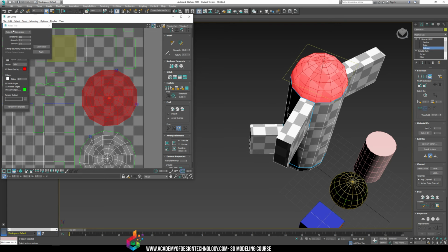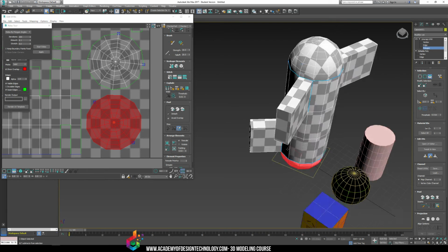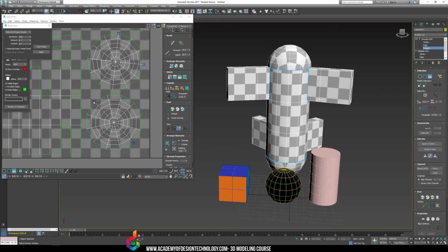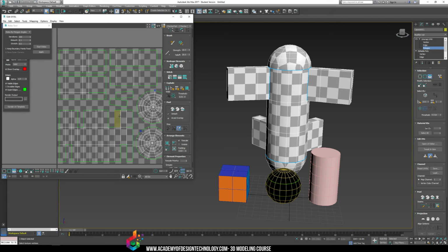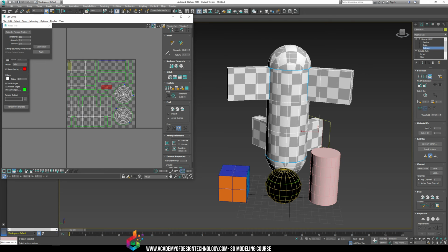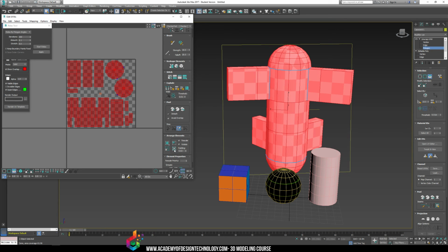But we can fix that with hopefully some polygon angle changes. Yep, relax by polygon angles. Worked a lot better. And there you go. Much, much better way of handling it. And you see we got the full thing textured. Everything is completely textured. You can also, when you go to Pack Normalize, click on Rotate as well. And this will rotate all the models to fit a lot better in. And you can even squish it closer.